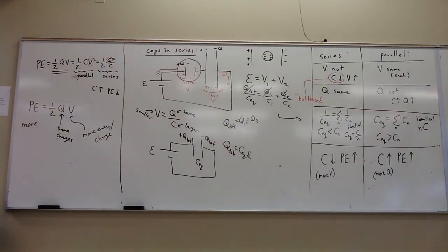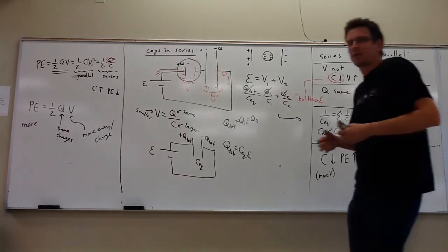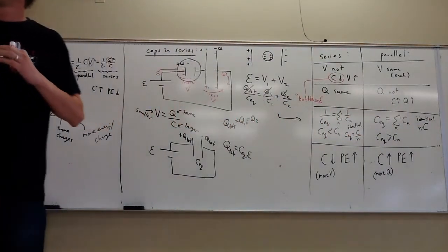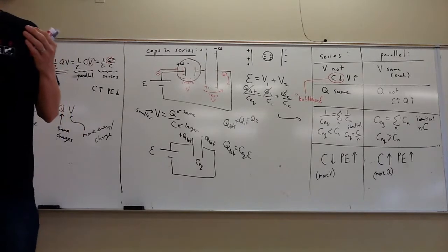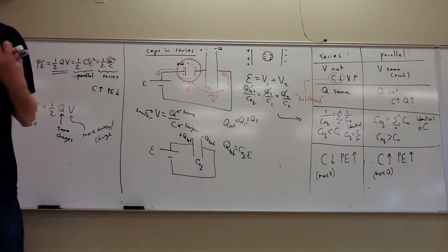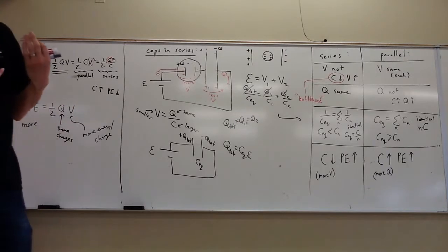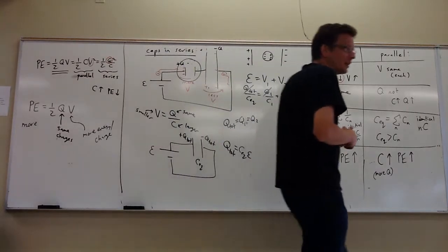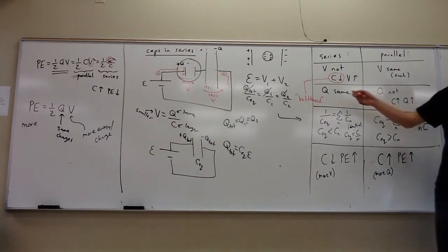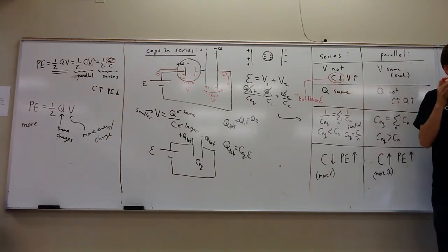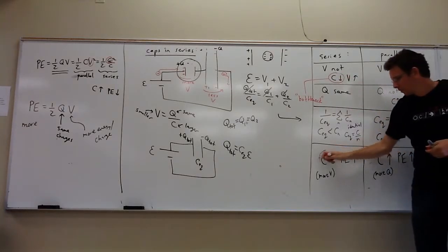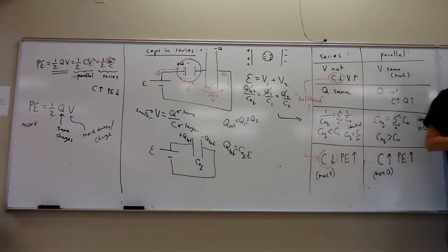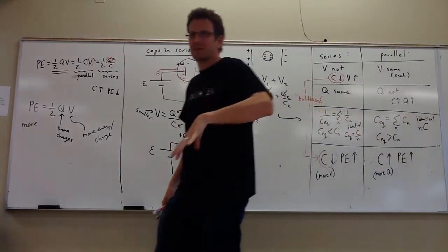Okay. So now what I want to do is show you that, and then to the extent that this is helpful, that there's a huge analogy between resistors and capacitors. I've already hinted at it, but I want to expound on that, okay? So we mentioned that in series, the bottleneck is where all the action is, right? The smaller capacitors, that's like the bottleneck, the bad storage devices. They get more voltage drop, they have more energy stored. The bad capacitors, right?